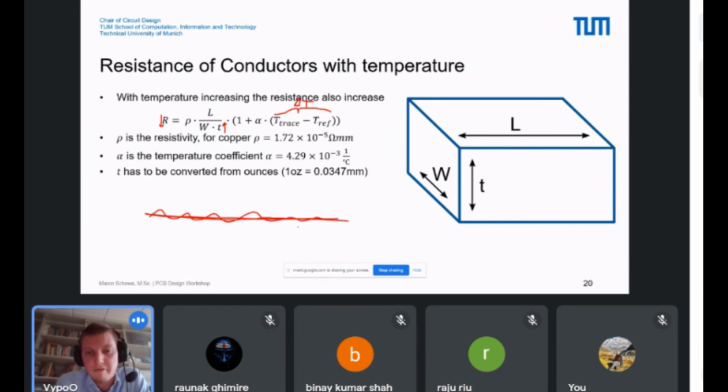But normally you will not have such high frequency on your board, because such high frequency or analog circuits are integrated circuits. You have only lines if you have an IC, let's say a 5 gigahertz IC for satellite communication, then you have only an output, an antenna. Therefore, only this trace is important for you, and then you have a digital output. This is a normal case, what you will have. And for this antenna, you need a matching network.